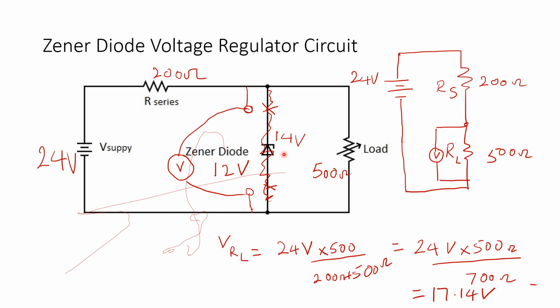All right. So just to recap, how do we check for potential voltage regulation? We remove the diode. In the lab condition, we will measure, but here we want to calculate. So to calculate, we use the voltage divider method. So we take the supply voltage. Let me write that out in the generic form.